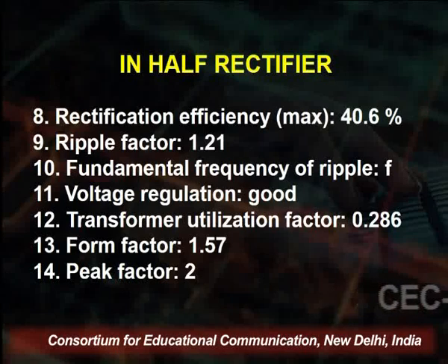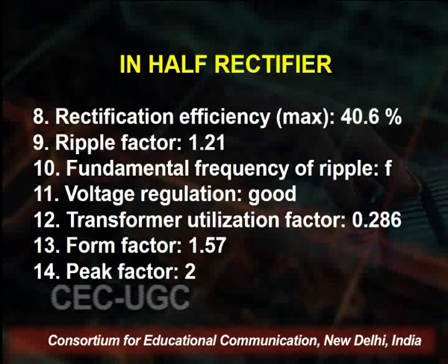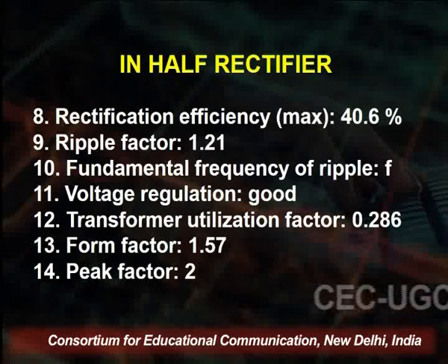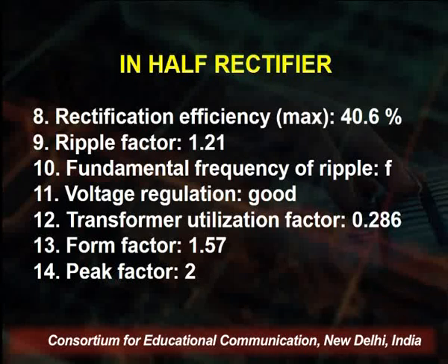The rectification efficiency must be 40.6%, ripple factor 1.21, voltage regulation will be good, transformer utilization factor must be 0.2, form factor 1.57, peak factor 2.